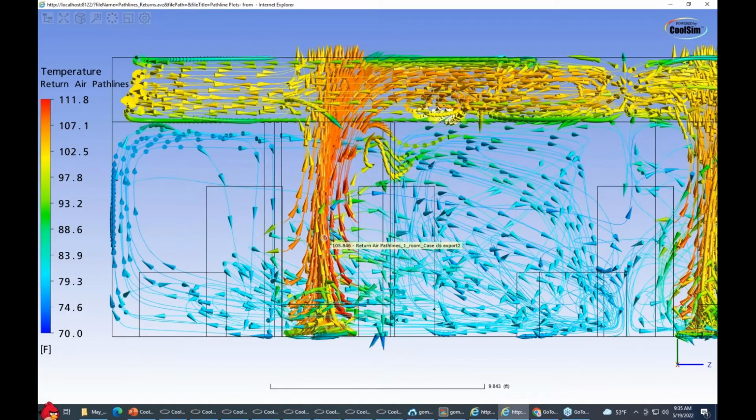It's important to look at the hot side in the data center, not so much the cold side, but the hot side. Where is the hot air going? What are the issues? So here we have the air coming out of the servers and up and going into the ceiling plenum. A lot of it is exiting correctly, but a lot of it is also going out and creating a pressure gradient in the hot aisle, because we're venting to atmosphere. Effectively, what's going on here is the servers themselves are the only things moving that air. When you have a crack running, it's pulling it because it's connected to the ceiling plenum. But here we're just dumping air into the room and venting the hot air to the atmosphere.